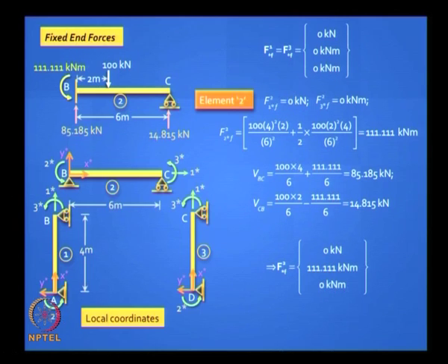You have only one moment there, because here you are accounting for the fact that at C there is a hinge, so you do not get a moment. Does it make sense now? I have taken care of the hinge, but I am still keeping my full-fledged 3 degree of freedom matrix, but I will take advantage in the next situation.